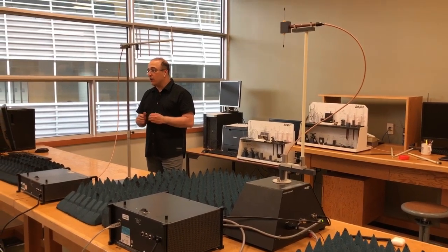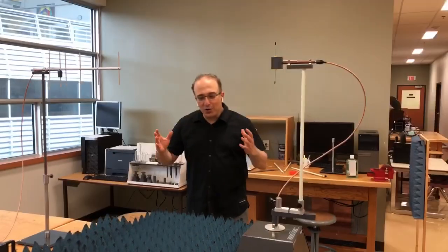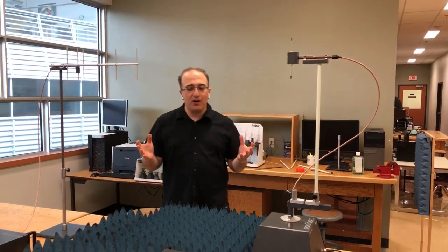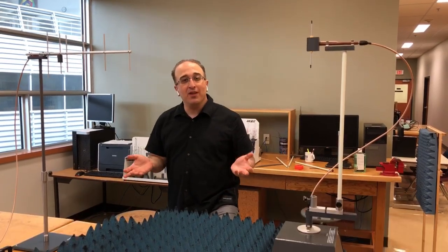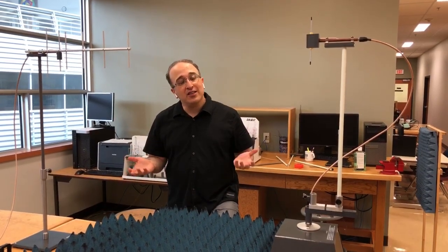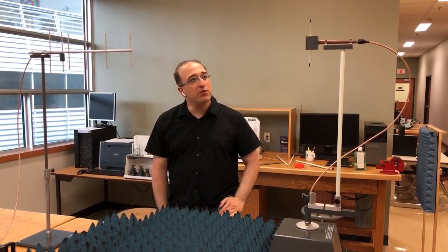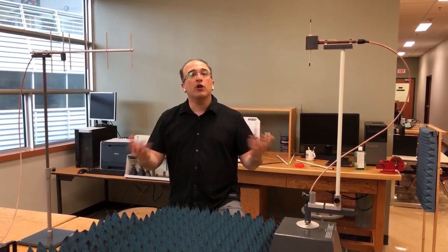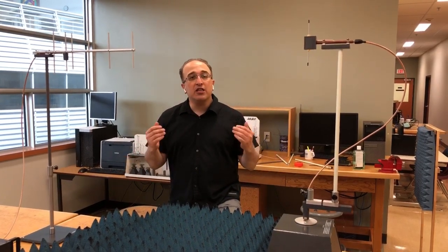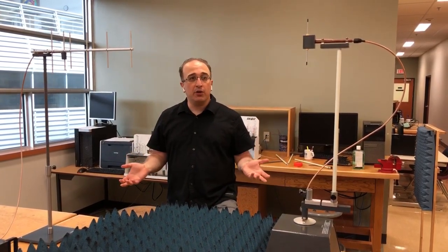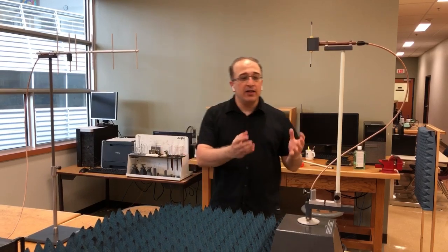Okay, now this is done. So what happened so far is that we measured E-plane, and in particular, our first E-plane measurement was co-pol. Then we measured cross-pol E-plane, and now this setup is for H-plane measurement. Now we're gonna go to the last one, which is cross-pol H-plane, because the antenna is gonna be still in its